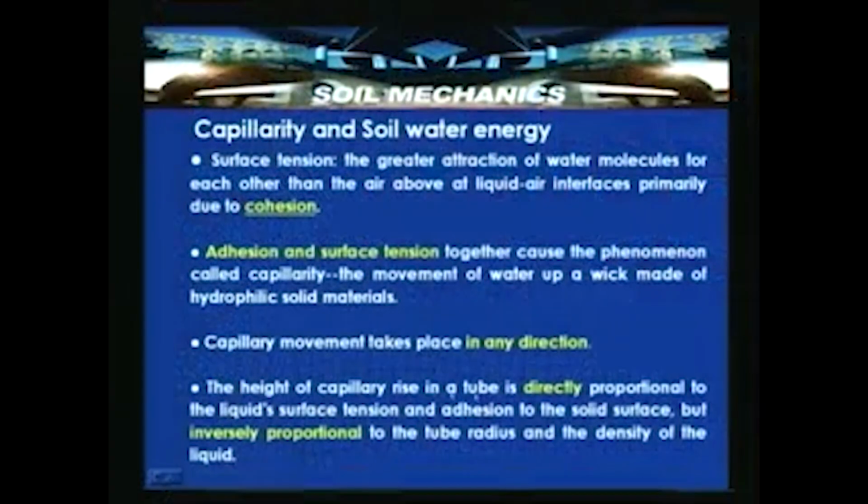The height of the capillary rise in a tube is directly proportional to the liquid surface tension and adhesion to the solid surface, that is very much important, but inversely proportional to the tube radius or diameter and the density of the liquid. So, inversely proportional to the density of the liquid, because in the derivation we have discussed the density which is in the denominator. So, inversely proportional to the density and to the diameter.